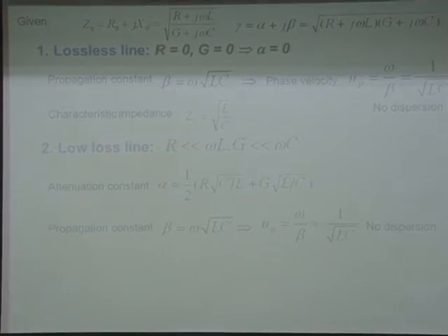And after doing this Taylor expansion, you can calculate the attenuation constant, and then you can also calculate the beta, the propagation constant, and deduce the phase velocity.